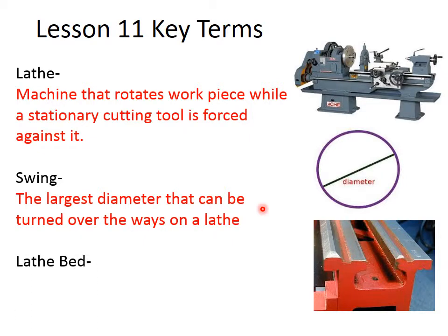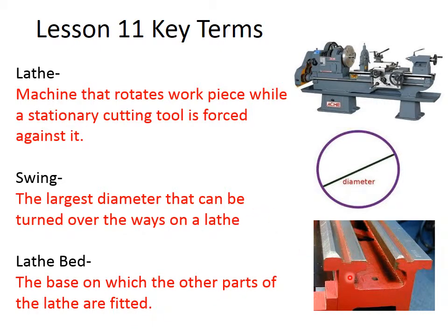The lathe bed is pictured down here. On the lathe bed, you have these guides. These are the bed ways. These things are really important. They need to stay really good and clean. They need to be oiled frequently, so your machine parts can slide on them.